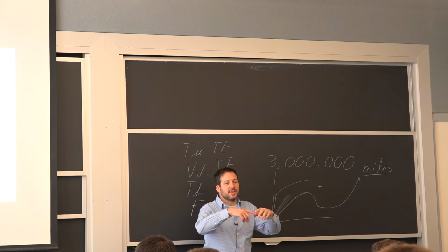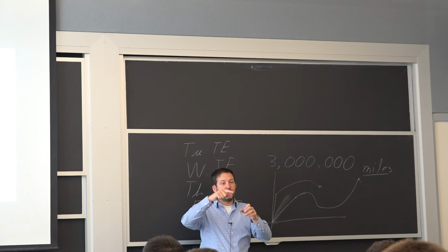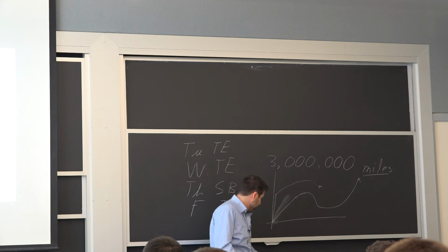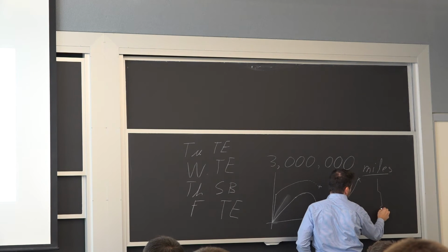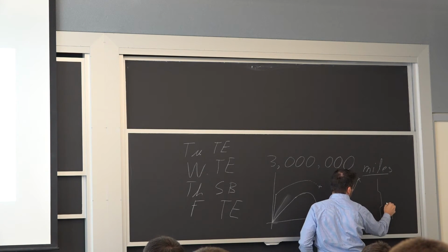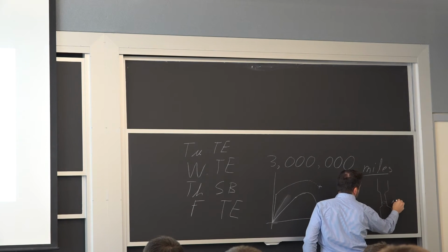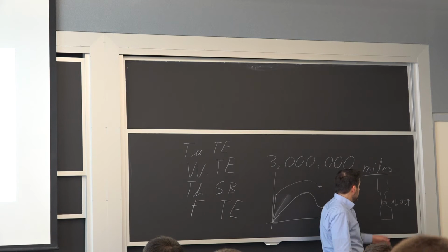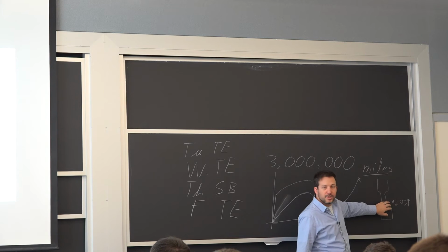So even though now you have less of a section of material, that material is stronger, and therefore the deformation starts to continue in other locations. That zone becomes inactive. So visually, essentially, I'm saying if I have a dog bone specimen here, and I try to deform, and there's a little bit more strain in this section, so A is going down, but the sigma yield or the flow stress is going up. So to the extent that this is going up sufficiently more, the deformation here stops.